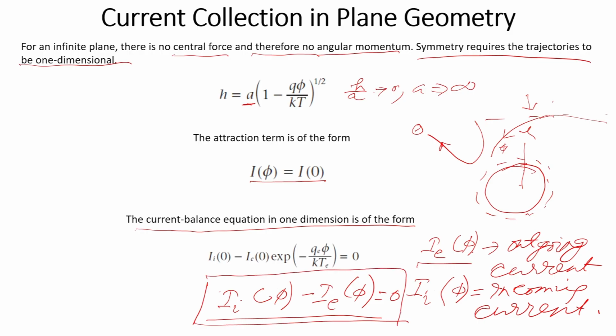In our future sessions, this will be the basic equation, called the current balance equation, and we will derive the expression for the currents. We will consider different components of the currents. We have taken just a very simplified case, so we will take more complicated cases and show how the spacecraft gets charged and a potential is built up. This is related to surface charging. We are now considering only the surface of the spacecraft, so this is known as surface spacecraft charging.